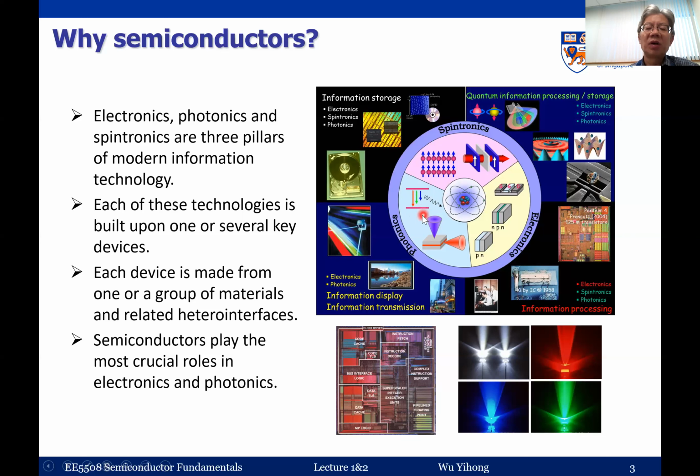And we can have another type of light, basically we call laser, in which the phase actually is synchronized. So in this case, we have a coherent light, just like a laser, right? Both the spontaneous light source and the laser can be implemented by using semiconductors. For the spontaneous light, we have the light emitting diode, we call LED. I think some of you may know this. And of course, for laser, we have the laser diode. It's the same type of p-n junction or a little bit more complicated p-n junction. For example, you may have a multi-layer, not just two layers.